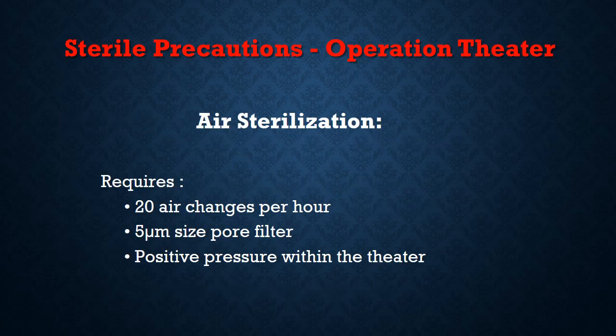So in the operation theater, the common things, this would apply to your dental surgery also to some extent. Air sterilization or laminar flow in the operation theater prevents outside dust and contaminated air from entering the operation theater and expels the air in a certain laminar flow. 20 air changes are required for an operation theater per hour.